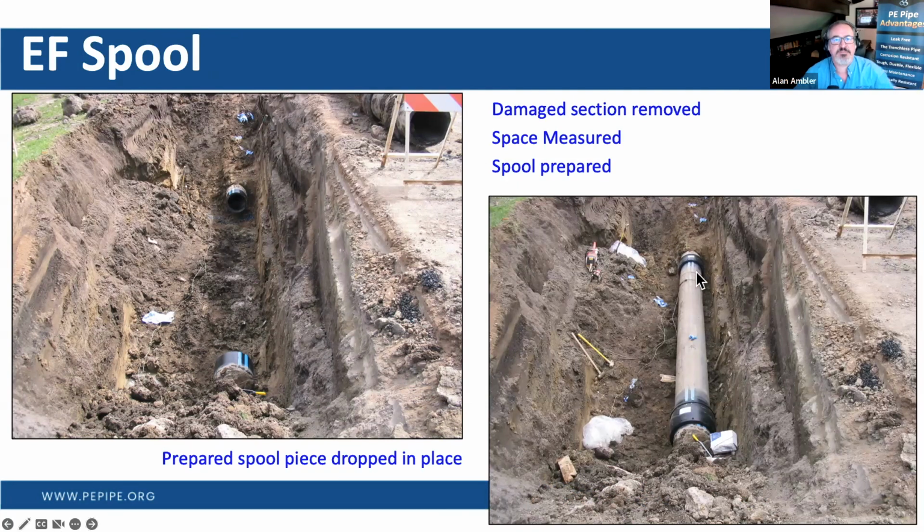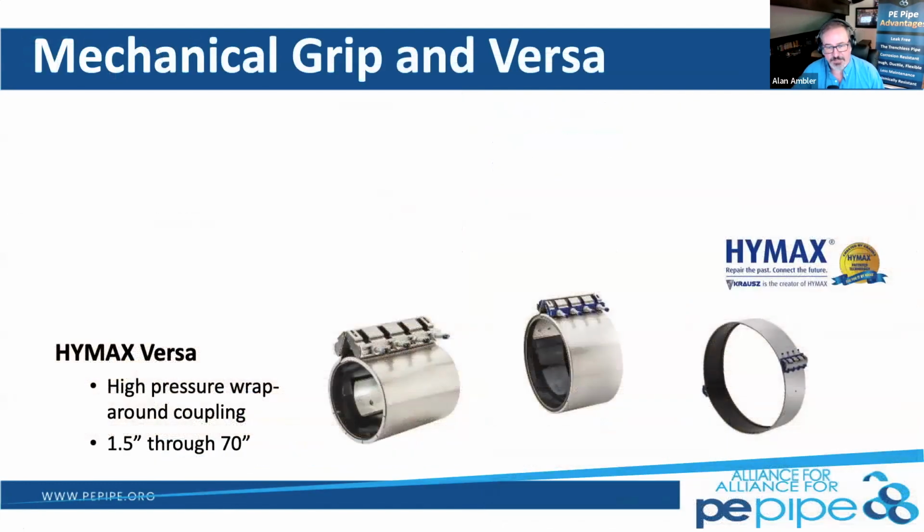Fire those couplings up after properly preparing. We're scraping that pipe and making sure it's inserted in the proper stab depth and everything that we need to be able to come through and do that connection properly to replace that pipe.